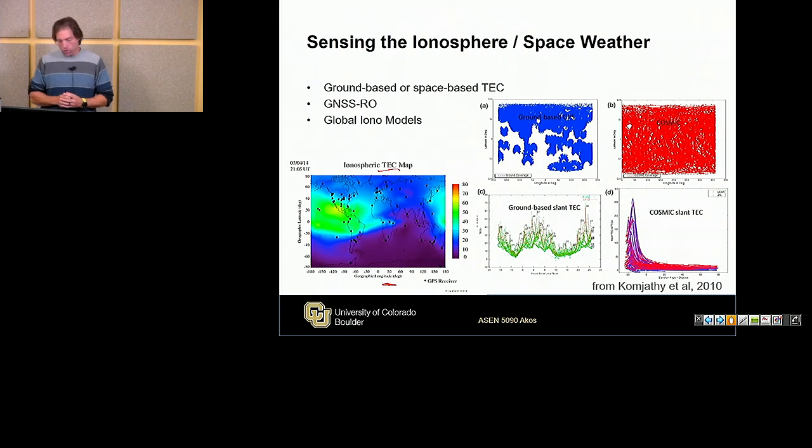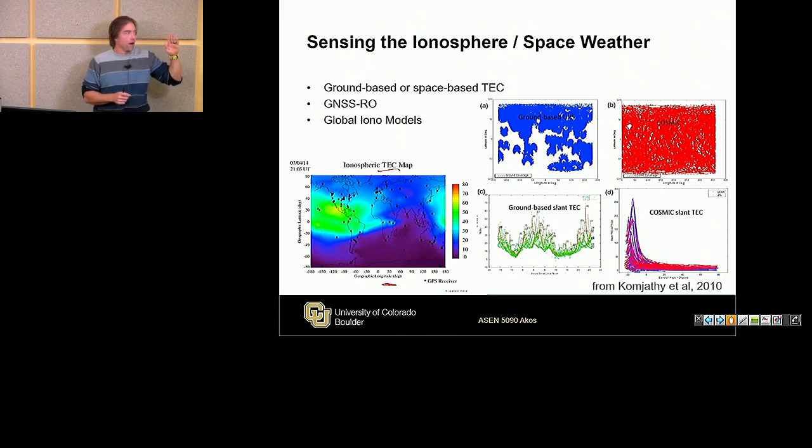This is critical for systems such as WAAS or aircraft landing. When I have to say I want to use my landing system for GPS, if I'm getting delays because of the ionosphere slowing my signal down, so the range of the satellite looks longer, it's distorting my position between one aircraft and another aircraft. It causes problems, particularly on the landing system. We need accuracies on the order of meter, sub-meter kind of levels to see what happens.